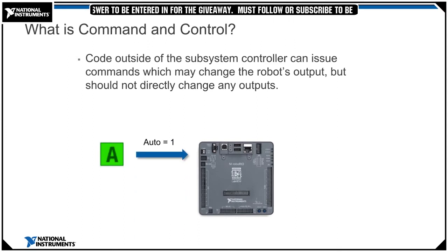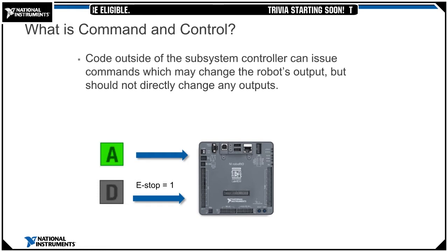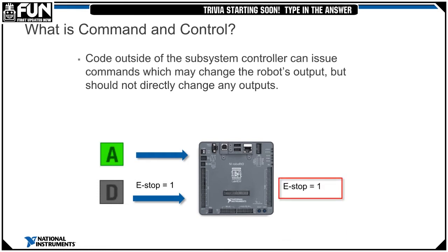So robot game code pretty much consists of autonomous and teleop, and typically needs to update set points and react to the states of different mechanisms on your robot. For autonomous, it's really common to define the robot's operation as a sequence of operations, right? Drive over here, pick this up, carry this here, drop it off here, etc. These commands can be wired sequentially with additional logic to quickly build complex routines, such as deciding, oh, I want to go to the left side of the switch or the right side of the switch.